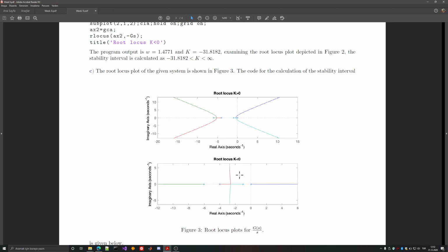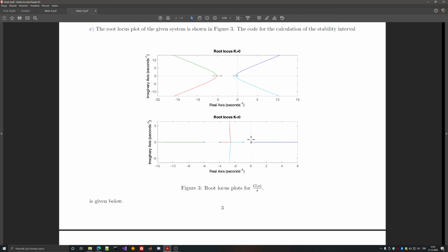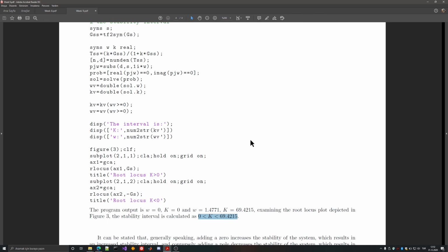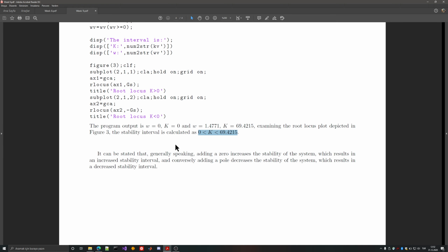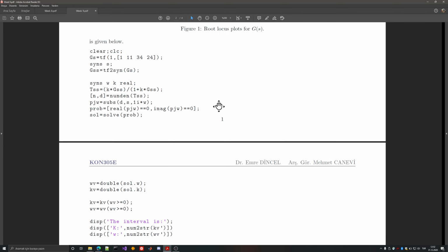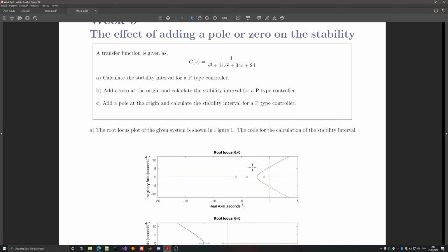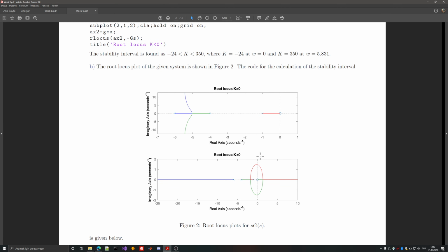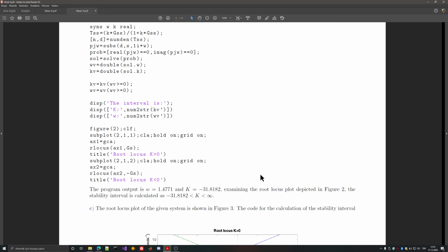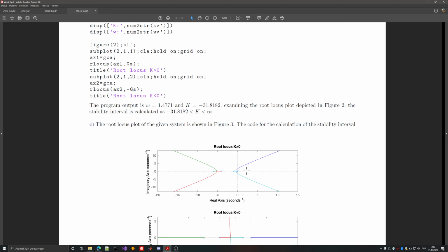So I can see now that adding a pole will narrow down the interval, and adding a zero will most likely help me out. So a better thing here is to consider adding poles on the left half plane, but look at the margin, because if I place something on the origin or j omega axis, since this is the critical point, it will be the worst case for most of the time.